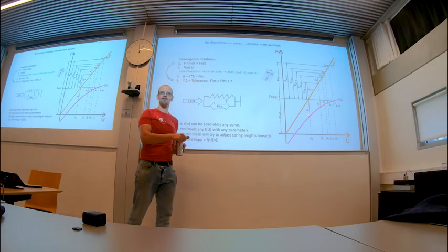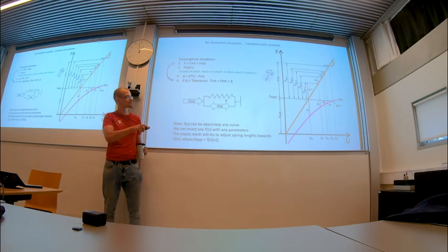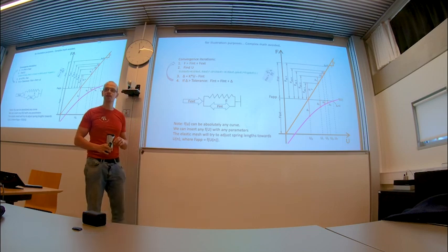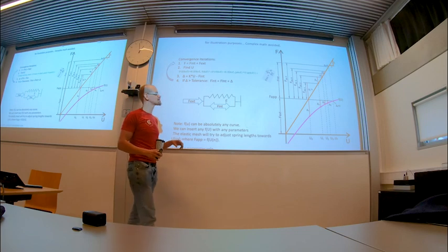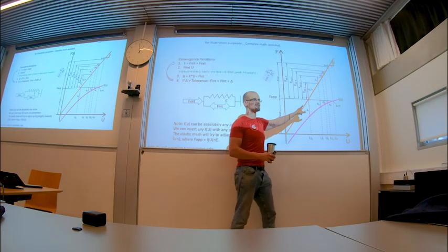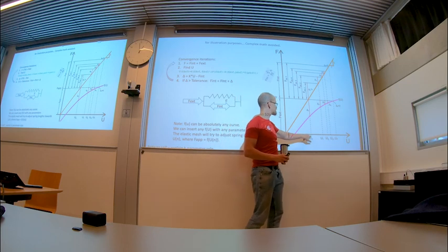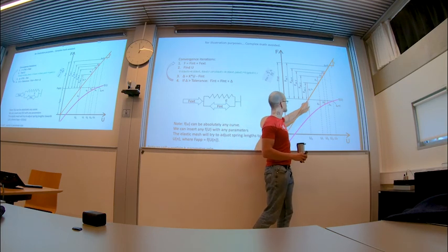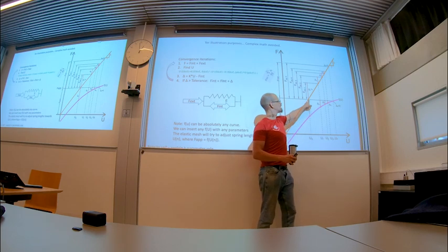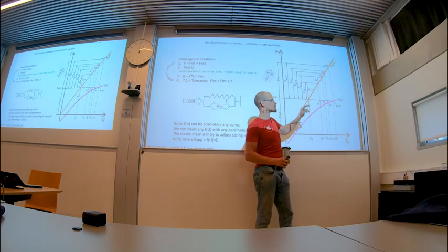Have you seen this before? These increments of error reduction. That's how all the plasticity formulas are solved. Technically, there are different methods of choosing how big the next step will be, because you have some plastic correction happening here. This is the elastic prediction, and this is the physical or plastic curve that you want the element to actually follow.